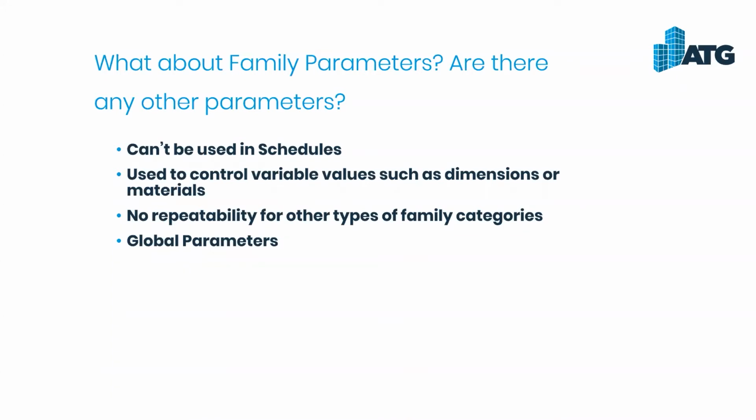That is very possible. For a lot of companies, they don't do that though. But if it is something that you want to schedule, then you may want to consider using the shared parameters, because again, the shared parameters can be scheduled, whereas you're not going to see that height, width, and depth as some options to create. You'll see a lot of the family parameters being created when you're initially developing those families. And as you can see here, they can't be used within schedules. They're used to control the dimensions or materials. Again, materials can be a shared parameter as well.